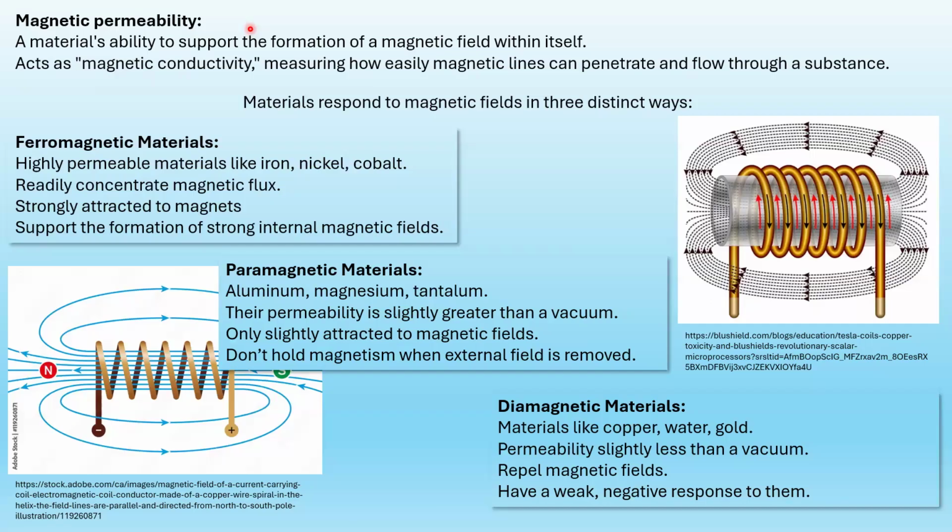How permeable the wall is, which means how the wall lets the house breathe. When we are talking about running wires and disturbing the exterior walls, where they have to have the vapor barrier, you might want to research that, because you can do a lot of damage. You might know a lot about electricity, but if you disturb the wall in the wrong way, and if you don't patch it up or repair it properly, then you might install something that is going to work properly, but you're going to cause a lot of damage.